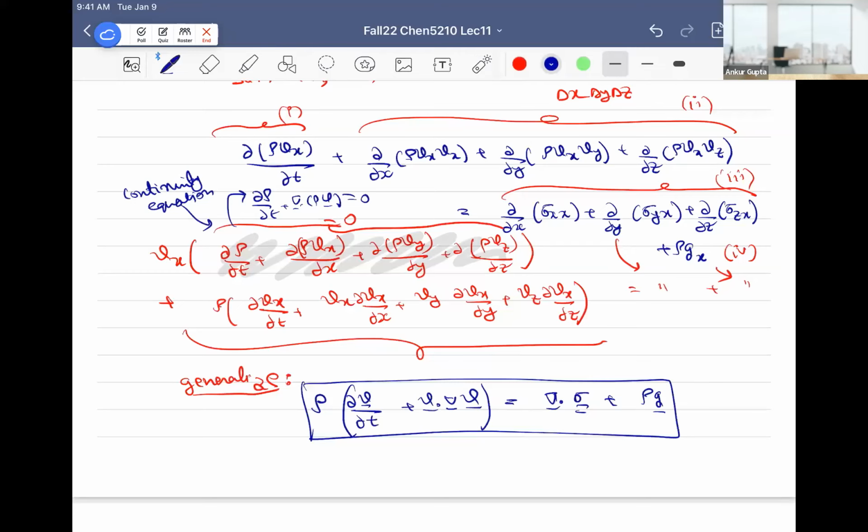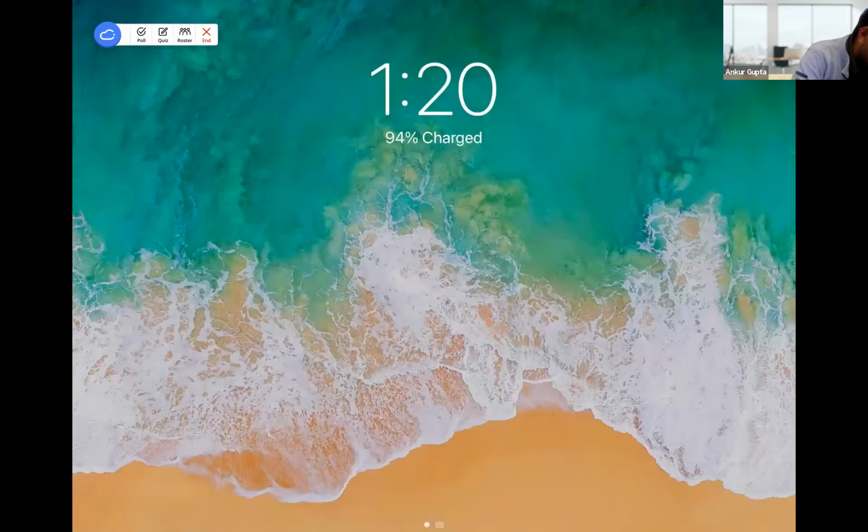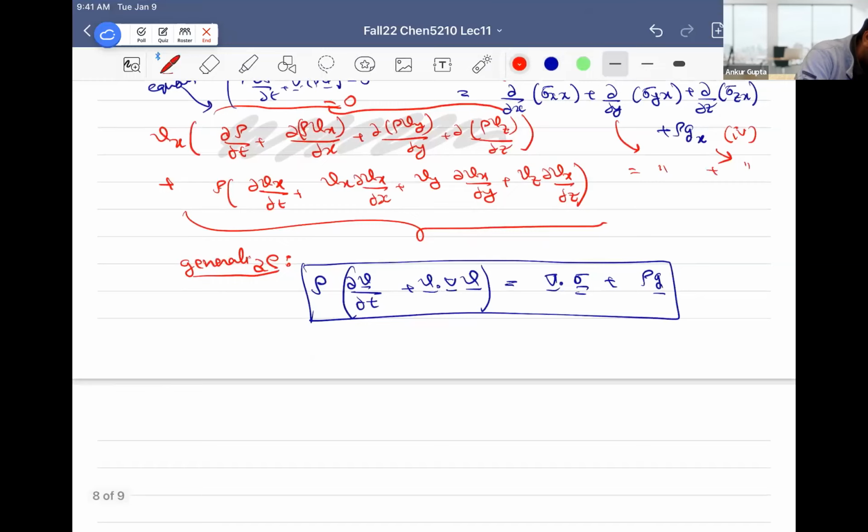There is another question? Yes. Correct. So what is this V dot del? This V dot del is sometimes known as an operator. Basically, this is Vx del by del x, plus Vy del by del y, plus Vz del by del z, and it's being operated on a velocity. Think of it like an operator which is being applied on some sort of a vector. It takes a little bit of getting used to, but you'll see it in time.